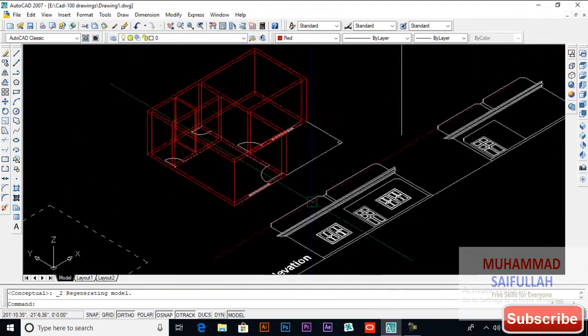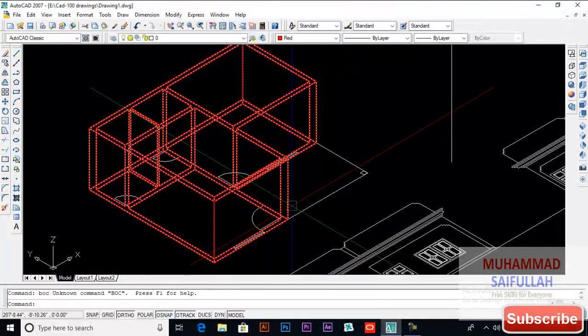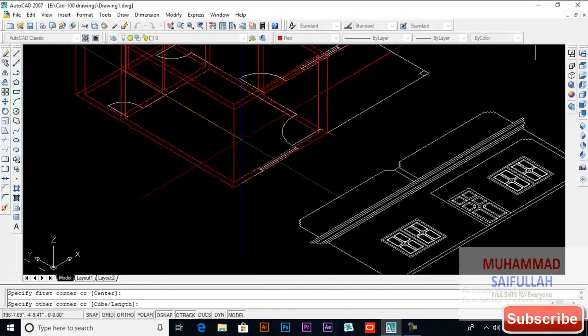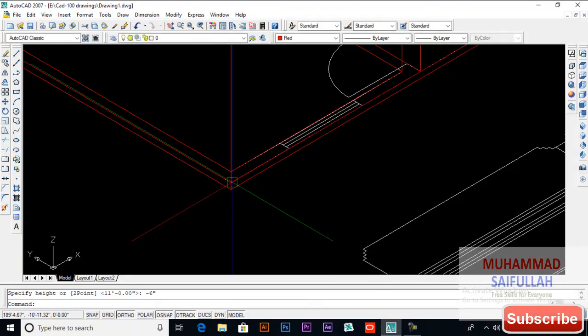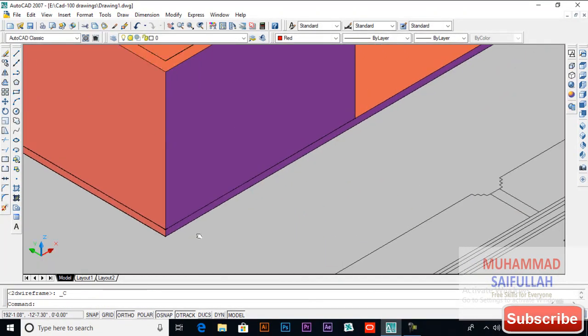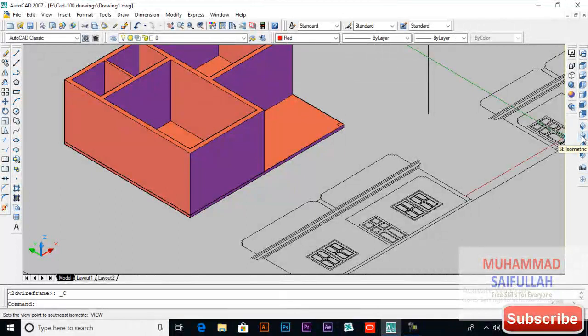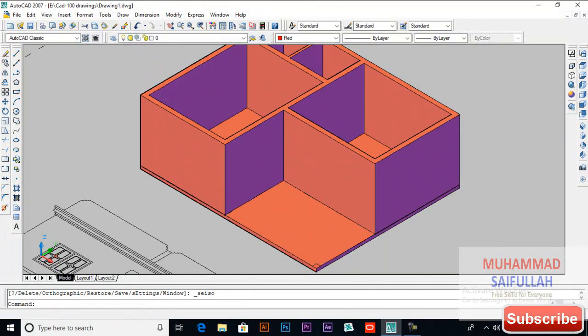Now for that plinth level I will draw a box here, BOX for box, from this point to this point, and I will give it a height of -6 inches. So you will see plinth level is drawn. You can switch between these views, so I will apply SE, southeast isometric view. I will again switch to 2D wireframe.